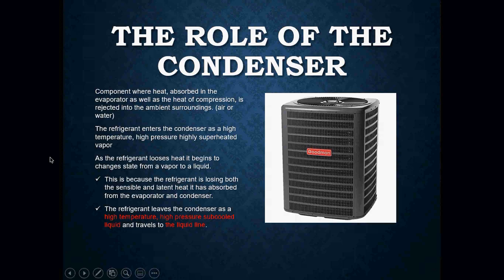Okay, now the role of the condenser is where heat that was absorbed in the evaporator, as well as the heat of compression from the compressor, is now rejected to the ambient surroundings. Our ambient surroundings can obviously be air. This is an air-cooled condenser. Air has to pass through our condenser coil in order for the condenser to reject the heat from the refrigerant.